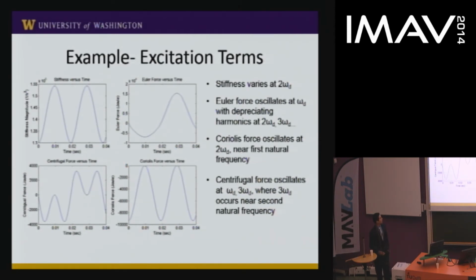And furthermore, this occurs in sync with the stiffness term, meaning when the Coriolis force is at a maximum, the stiffness is at a minimum. So that's an interesting result, as you're pushing harder as this thing is softer.